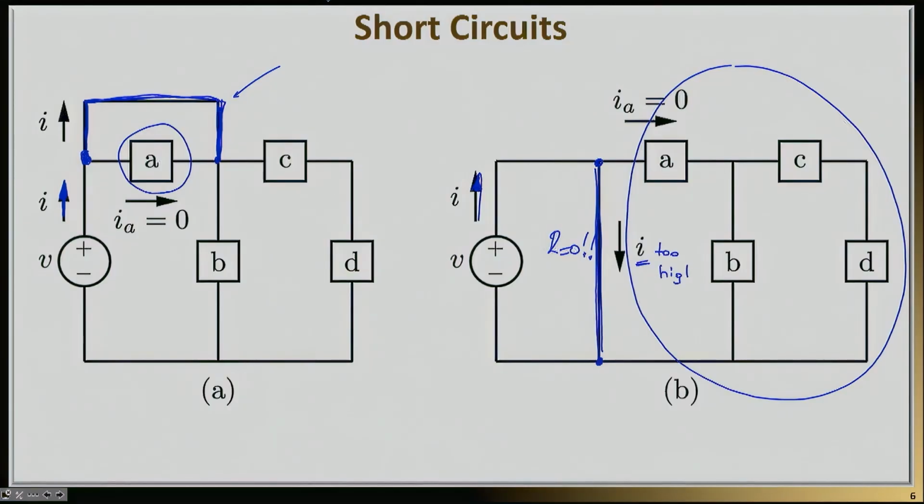And if this current I now is too high, because you're forcing this current to go through a path of practically zero resistance, you may be up for some very, very unpleasant surprises. Something may get burned, cause fire, or even worse, cause injury or death. So you need to be very, very careful where intentionally you're introducing short circuits to bypass devices. You may actually create a dangerous condition. On the other hand, this short circuit here may not be intentionally introduced. Perhaps there was already an accident. Maybe there was some lightning. Maybe some fuse got burned in the wrong way, and therefore a short was created.